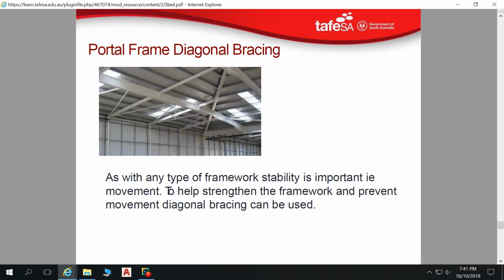Our fire shed at Montacute, which has just recently been built almost a year ago now, the bracing inside that just sags. So the builders built the place, but they had cleats on the end of the bracing. They installed it, but they can't tension it up because it's cleated at both ends. And when it's cleated at both ends, you've got to get it millimetre perfect.